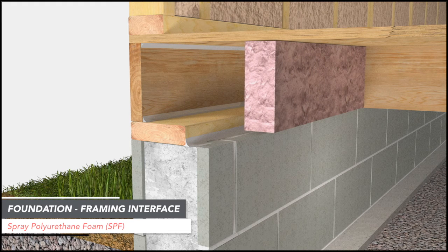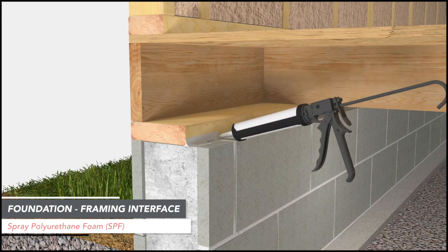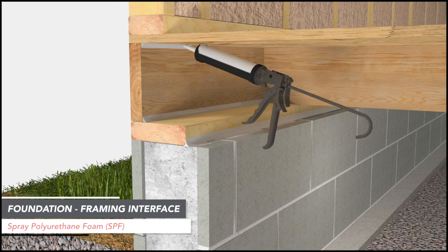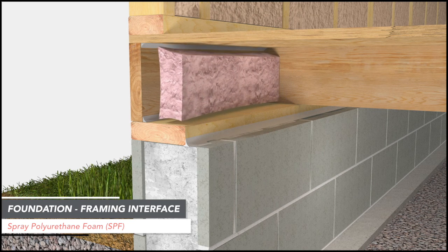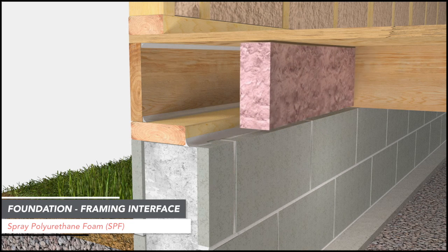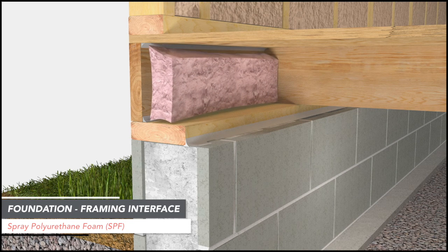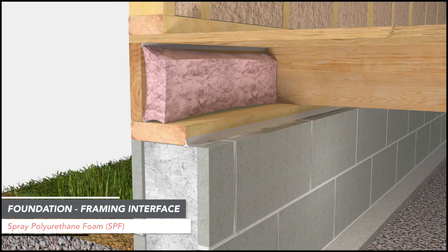Aside from the labor-intensive sealing required for removable batts, repeated removal and reinstallation of these fiberglass batts will ultimately damage this type of installation over time. Pest management professionals are not trained in the proper installation of fiberglass batts and may not reinstall them in the Grade 1 condition required by residential energy efficiency programs like Energy Star.